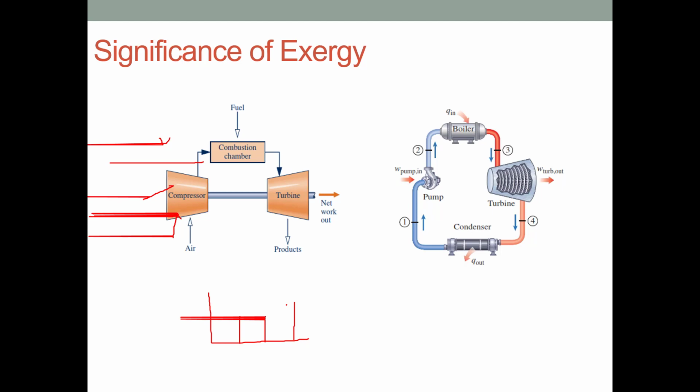So we'll try to see whether the lubrication for the bearing is okay. Is there any vibration in the gas turbine? Or it could be because of heat loss, so there could be poor insulation for the gas turbine. There could be countless reasons for the loss of the exergy. This is one significance of the exergy, that you can analyze each component of the system and see how much is the loss in exergy in each component. Loss in exergy means loss in useful work.